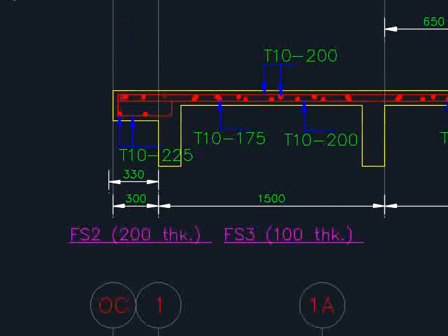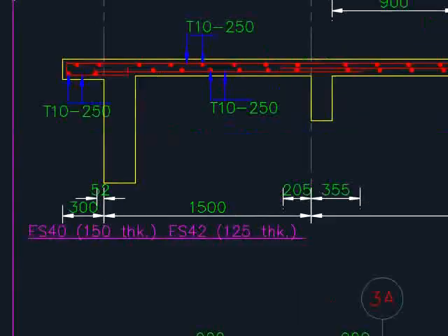The best way for it is to have every twist in terms of the corners have a longitudinal reinforcement bar. And you know that this one is meant for the architectural purpose. The loading acting on this part may not be high. You can actually reduce the amount of reinforcement bar. A similar design here, where you have a fin extended from the slab.